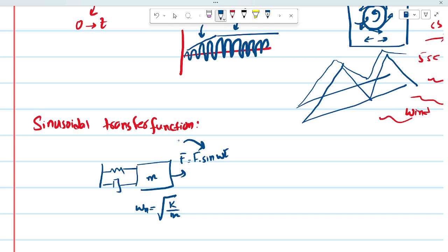If the damping is present, the portion of motion not sustained by the sinusoidal input will gradually die out. As a result, the response at steady state is sinusoidal at the same frequency as the input. With the presence of damping, the portion of the system outside the frequency of the applied load will damp out, and the steady state response will be at the same frequency as the applied load. That's why we are more concerned with the applied frequency.